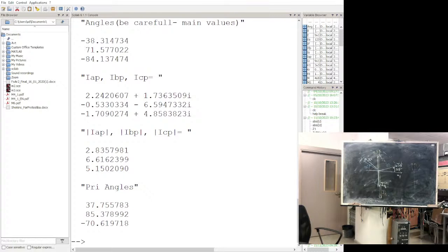In reality, you have some part of a synchronous machine at your customer, and this also brings additional complexity. The currents you will see in reality are close to this theory, but not exactly, because negative sequence will flow to the primary side only partially.